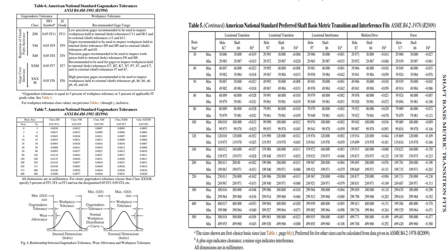And further, gauges are according to Taylor principles in the workshop. In a workshop area we have different gauges, and they differ from the gauges we use in inspection. So inspection gauges are different from workshop gauges, and the gauge tolerance values we get when we divide the tolerance values by 10.